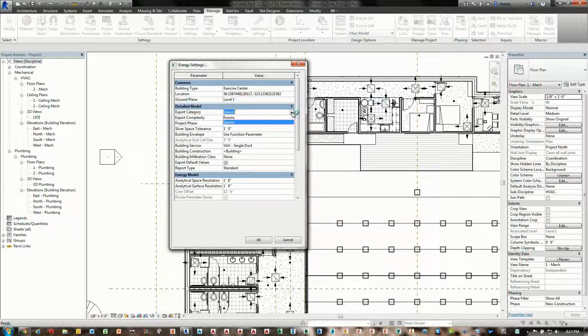So for the purposes of quick explanation, when we look at a room object and we place it inside our model, it'll obviously know things such as length, width, height. It'll know its restricted areas because of room-bounding objects such as system families, floors, walls, ceilings, things like that, roofs. But it doesn't contain the analytical information such as mechanical and electrical data. And so for the purposes of energy analysis, it is better for you to work with spaces and use spaces. Okay? So here we choose spaces.